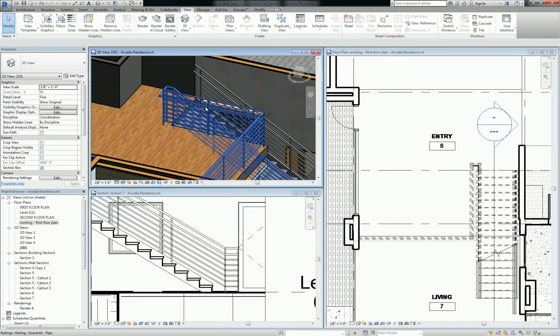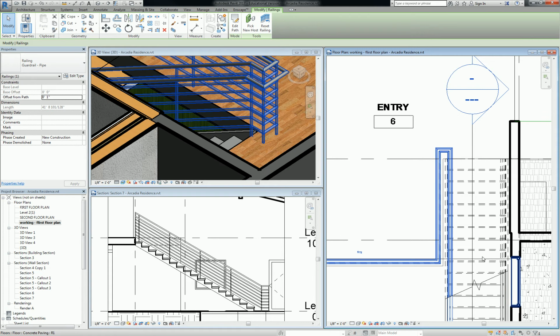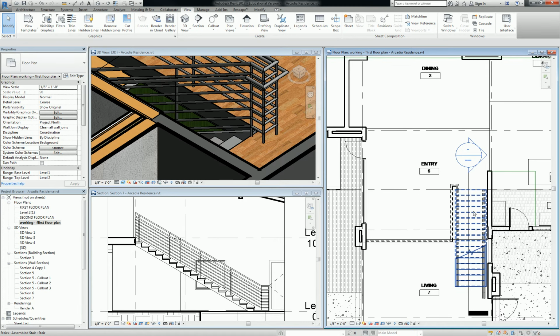I was just assuming because I remember when we were doing this in David's class, we basically couldn't get it to work. We just had to do like a workaround, like nudge things, like make them look like they fit. Yeah, well, sometimes it does like really weird things. It's actually behaving really well on me right now. Occasionally, if you do the extension thing where you just draw the line farther than the floor, it'll just say, screw it, I'm just going to be horizontal. You know, it doesn't read that it's a part of the stair anymore on occasion. So, you know, there are some things that you have to do in order to get it to work right. Oftentimes, like with this kind of stuff, I've just resorted to using Grasshopper on occasion.